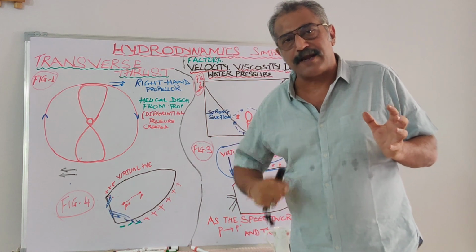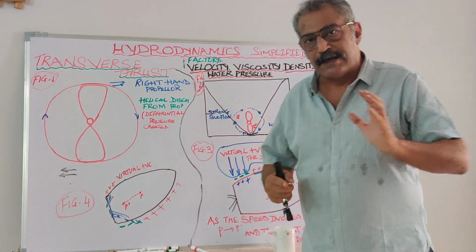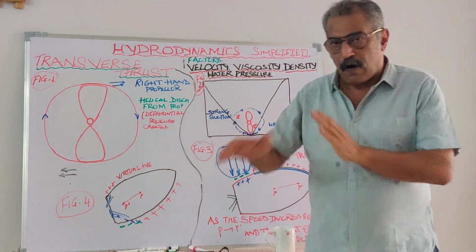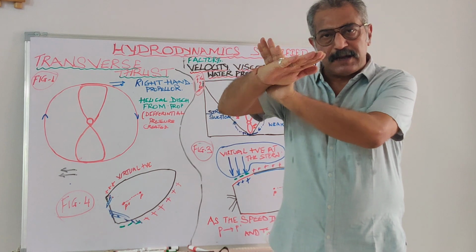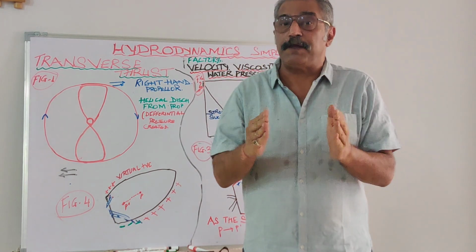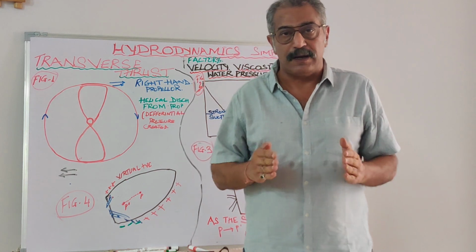One is because of the right hand screw motion of the propeller, and the water is getting displaced. This is helping the vessel to push her on the port side at the transom, and the bow cants to port. This is only applicable when the vessel speed is slow, as I repeated myself earlier as well.